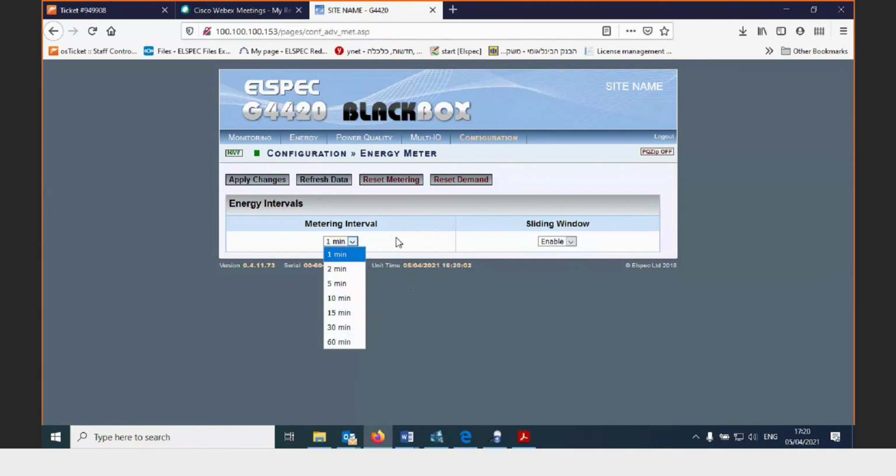Customers, I had an issue in Peru. Our agent reported that he cannot get in PQSCADA readings or exporting energy in 15 minutes. Now, when we looked at the setting of the device, it was set to 30 minutes. Okay, so it was saved in 30 minute blocks. So of course, after that in PQSCADA, it cannot export in 15 minutes.